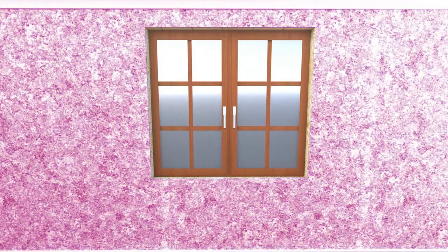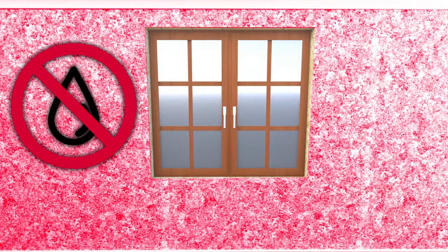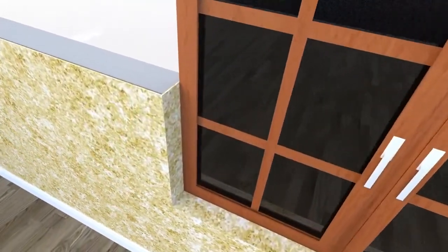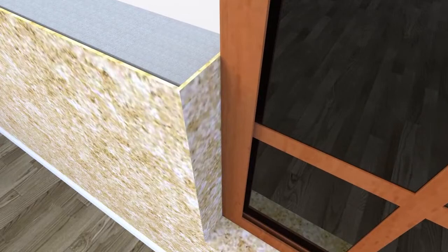Even though this system typically won't achieve performance in line with building regulations, even a small upgrade in thermal insulation can raise the internal surface temperature enough to avoid condensation problems. The minimal thickness also allows it to be used on space-constrained areas to ensure continuity of thermal insulation. In our example here, a solid uninsulated masonry wall has a risk of condensation across the whole surface, both the main part of the wall and at the window reveals.